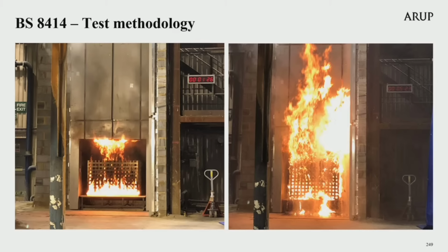The test continues for a further 30 minutes, during which time any observed flaming on the test specimen is allowed to continue burning. The test is stopped early if at any point during the test flames extend above the test apparatus, or if there is a risk to the safety of personnel within the test facility.